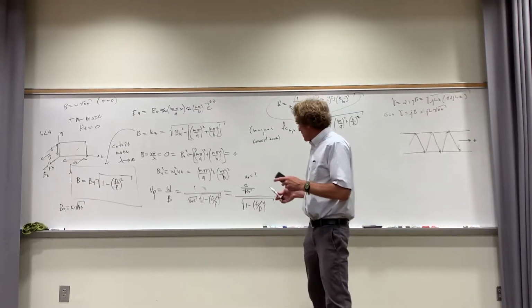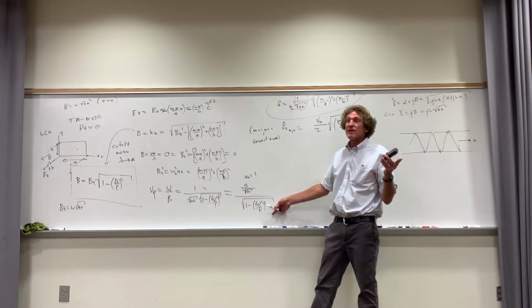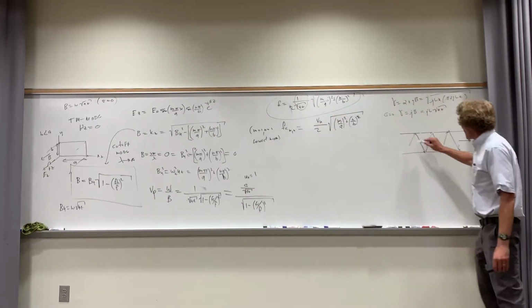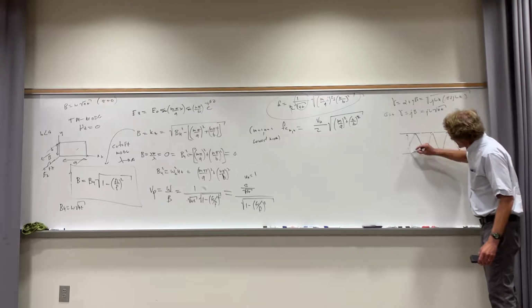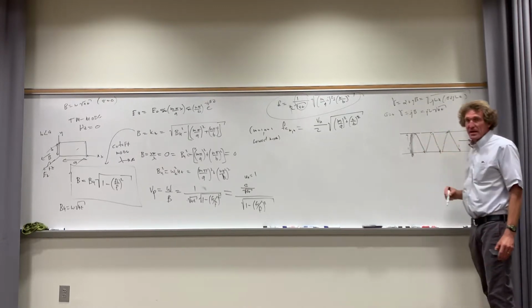And what does the phase velocity approach when f goes to fc? Class? Infinity, right? That means the phase velocity is approaching infinity. And that's what happens at cutoff. Literally, the wave goes from bouncing at an angle to bouncing just up and down, up and down. Nothing propagates, it just bangs back and forth like a resonant cavity.